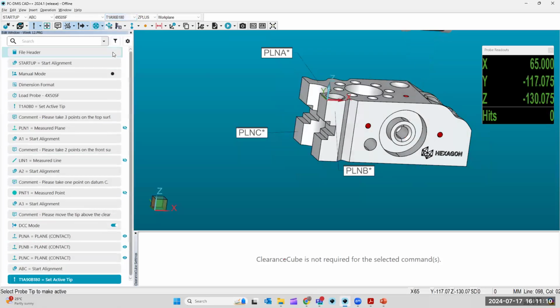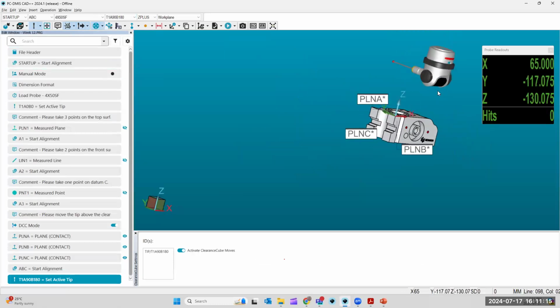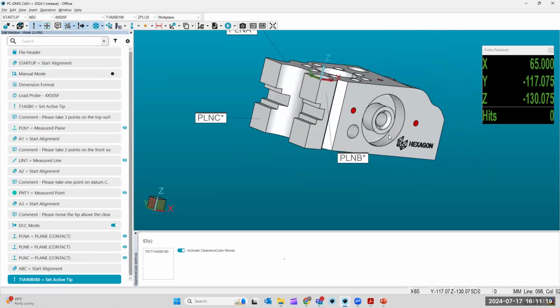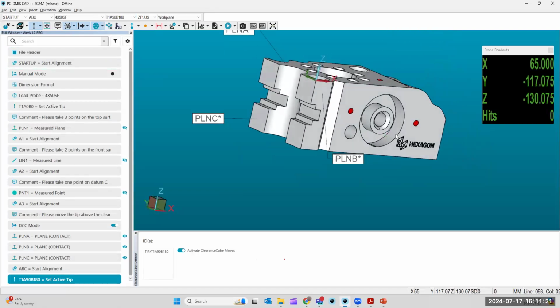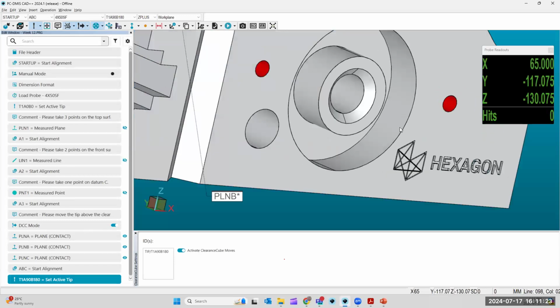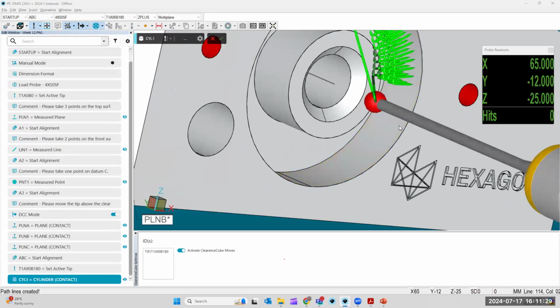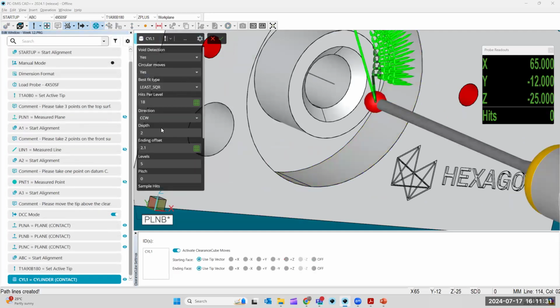As long as you have that tip built in your profile, it'll change the tip angle of the probe. That's one way to do it, or you can use the auto wrist, but that should not be enabled yet on your auto feature. Now I'm going to click near the outer part to ensure that my end offset and my depth do not get reversed.